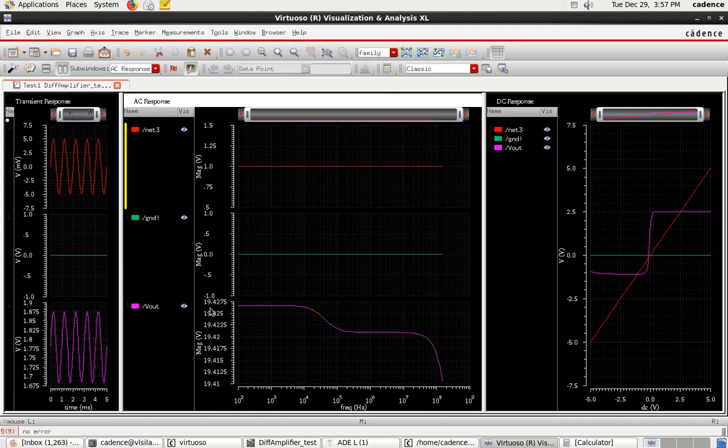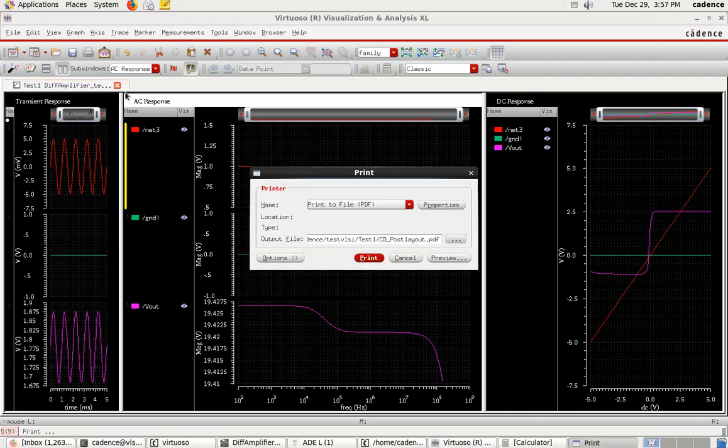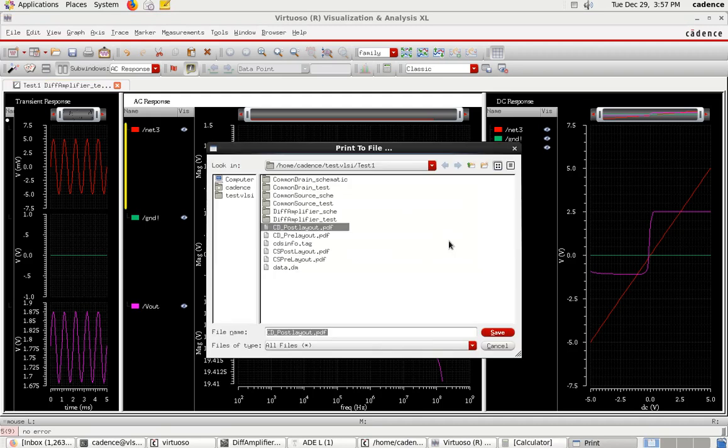You can check here also, same thing you can check from here also. See, the gain is around 19.42, so that much amplification you're getting. So this is how a differential amplifier works, right? So a differential voltage would be amplified to a certain range, right? That is around 19.42, right?